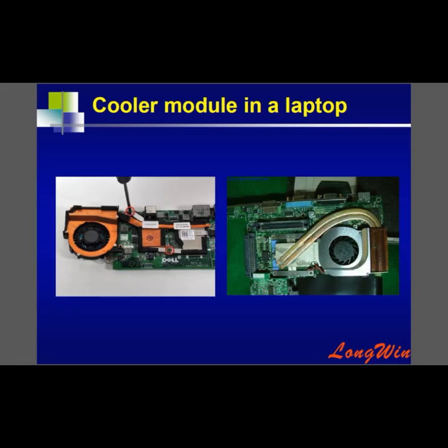And then the heat will pass through the TIM material, such as the thermal grease, and pass through the copper plate, and then the heat pipe, all the way to the fin. And then there's a fan, and then the wind will dissipate the heat away.